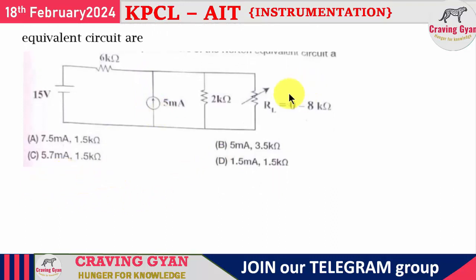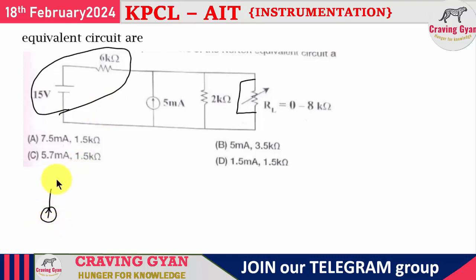we have to remove the load and provide a short circuit path to it. And one more thing, this 15 volt 6 kilo ohms, I am going to denote something like this. I am going to write the equivalent current source of it. If I am writing the equivalent current source, what I am going to get is 15 divided by 6, that is 15 divided by 6 milliamperes, or 2.5 milliamperes.